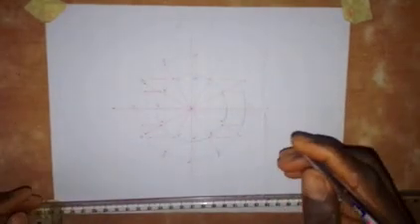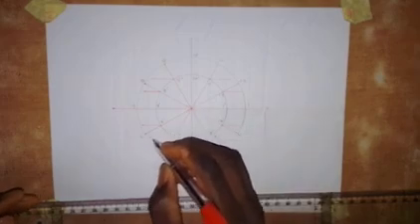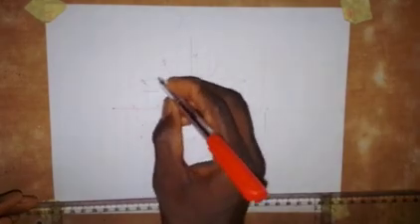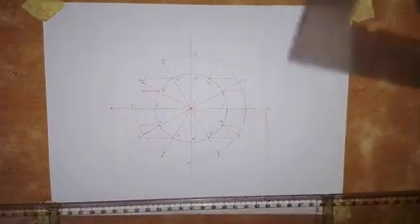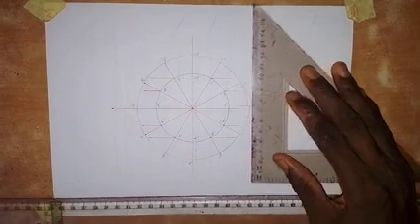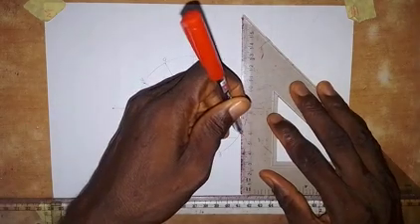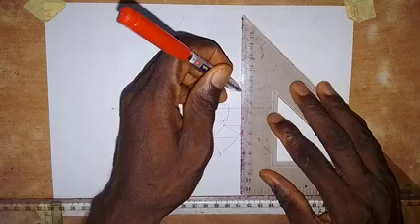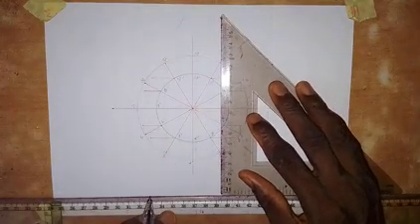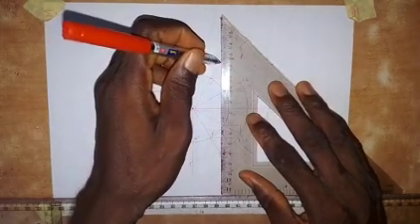Alright, so for the points that we have on the major axis, that is 2, 3, 5, 6, 8, 9, 11 and 12, we have to draw a vertical line. So coming to that of 2 and 12, I will draw a vertical line from here to touch the horizontal line, and I will draw from 12 to touch the horizontal line. And then for 3 and 11, I will draw a vertical line from 3 up, and then from 11